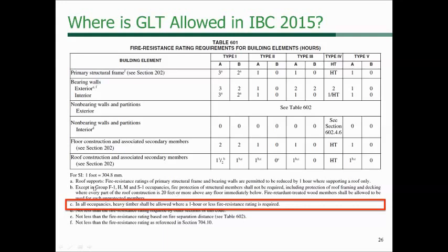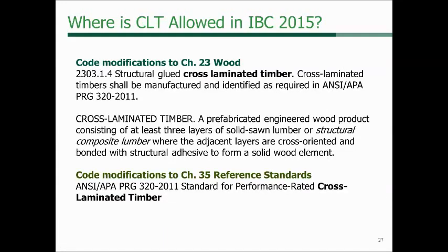And there's also footnote B, so for type 1A, footnote B allows for all occupancies except for those listed here, if your roof is 20 feet or more above the floor below, fire retardant treated wood to be used. So in type 1A, it allows fire retardant treated wood for the roof construction. These are just some caveats, or some exceptions, to the non-combustible construction.